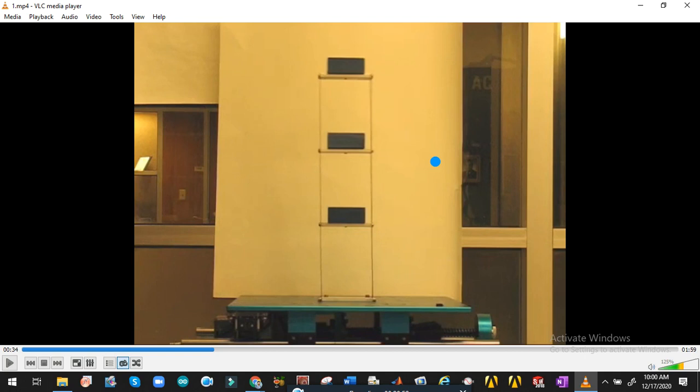Now, if that particular frequency is matching a certain mode shape of that building, it will be vibrating at that mode shape. If I am exciting the system at multiple excitation frequencies, for example, this is one shaker, and I attach another shaker here, now there are two excitation forces.